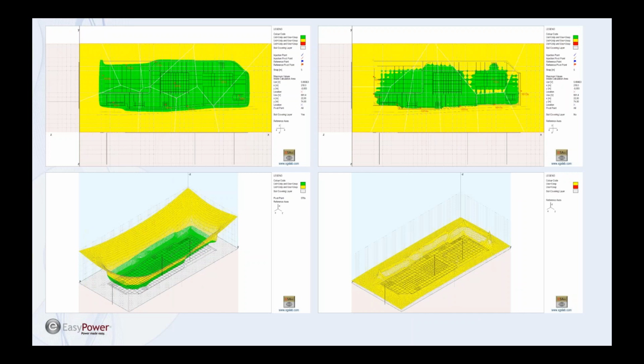So based on that ground potential rise that we just saw on the last slide, the program can do calculations for each 1 meter step in there, and each 1 meter, 2 meter, 3 meter touch within there, and it can do safety calculations for step and touch. The step and the touch allowable voltage are calculated per the IEEE 80 equations.